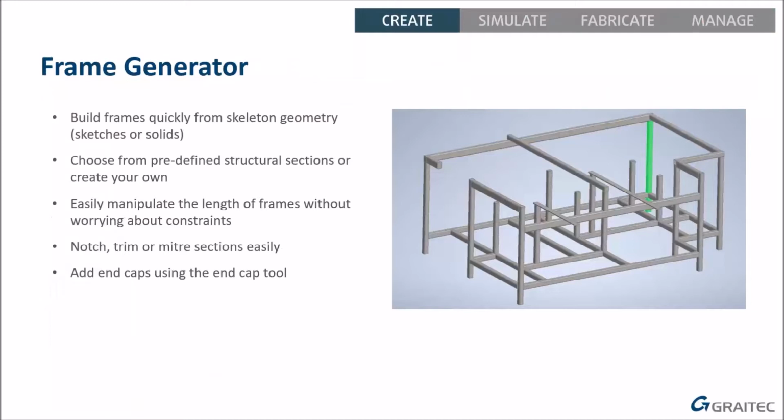All right, so in this webinar today, we're going to have a look at the frame generator. Now, if you haven't used frame generator in Inventor before, it's quite a good tool to use. It's obviously good at making frames, as the name implies, but it's the way that it makes those frames, because it's a lot easier than having to model each of these frame members individually and then bringing them into an assembly and then trying to constrain everything together, only to find that you now need to miter the ends together, so you're having to add additional cuts in, and then you can't get the weld gaps right, and perhaps you need to increase the length of one frame member and then all the frame members move.